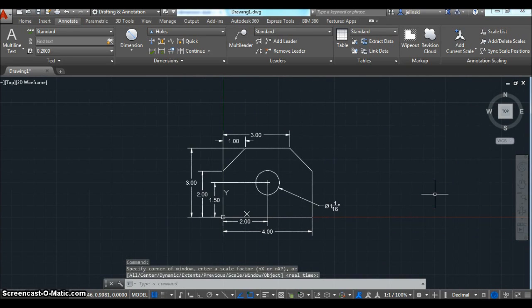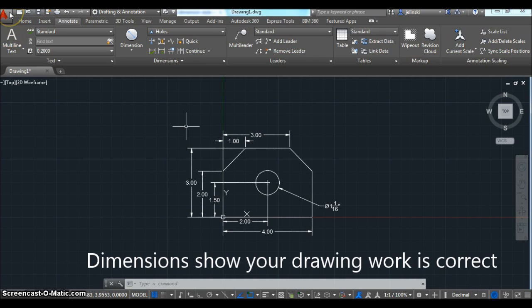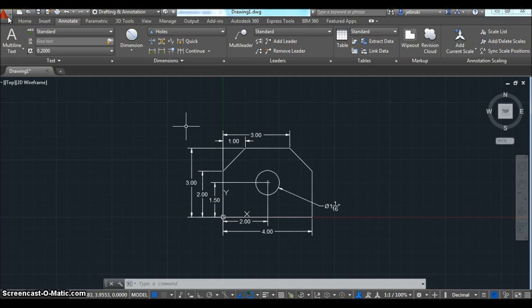Okay, now I'm just checking out my drawing, making sure I have everything correct, and it looks like all my dimensions checked out. Now your dimensions aren't something that you make up. It was just something that was based on the drawing that you made. So now I'm ready to go ahead and save my file, and this is really important that you follow this direction. I need to save my file as a DXF. That's the file type that you can import into the program that'll cut this on the water jet for you.